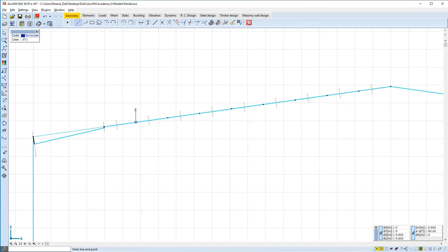Because of the pitch of the beam, this is not an easy task using graphical input, so we can use the perpendicular tool from the editing assistance functions, with which we can only draw perpendicular lines after we have defined the base vector. Length is given by pressing L and giving the length manually with the keyboard.